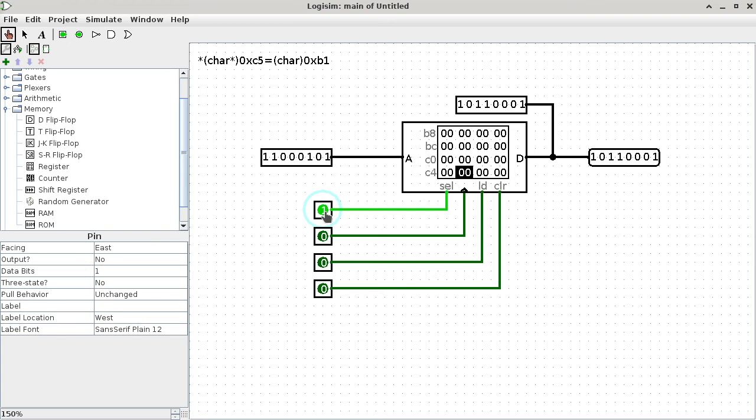All right, so that means in order for the RAM component, it's already in write mode at this point, okay? What it's doing is waiting for the rising edge at the clock. So what we need to do is to transition the clock from a 0 to 1, and right at that moment, it takes in whatever is at the D port and uses it to update whatever location is addressed by the A port.